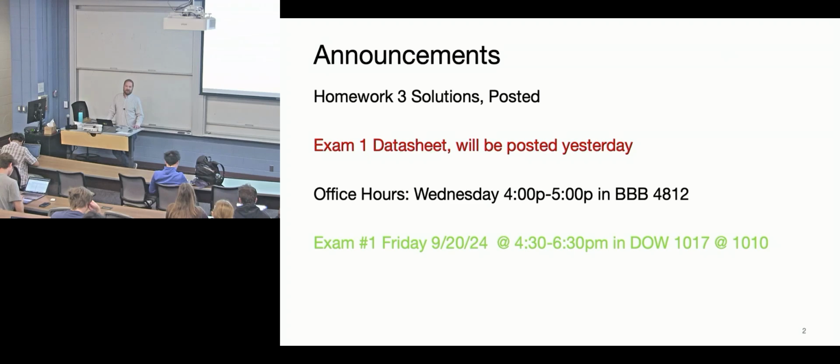What other questions do you have? Is everything in that data sheet crystal clear? Yeah. On the data sheet, in the radio control register, I'm seeing a difference between what's in the picture and what's in the text. It looks like send corresponds to bit 1, but in the picture it's bit 0. So I just wanted to see which is correct.